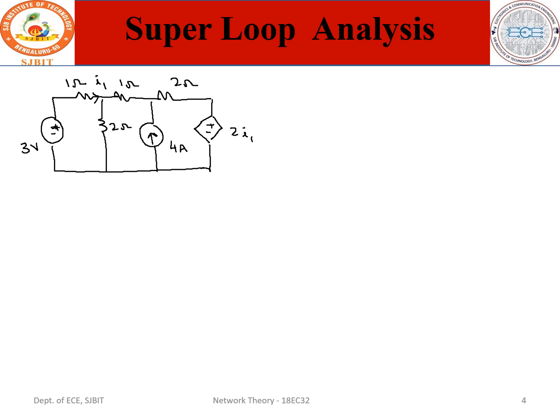In the exam they can ask a question like this: find the current in the 2 ohm resistors by mesh analysis shown in the figure. There will be 3 loops here. Assume the loop currents. You can assume the loop current like this. This is one loop current. So I am assuming this loop current as I1, this loop current is I2, and this loop current I am assuming as I3.